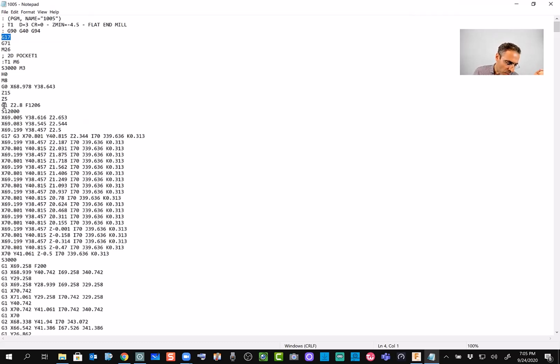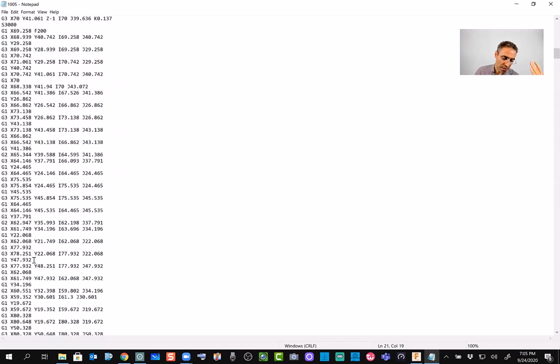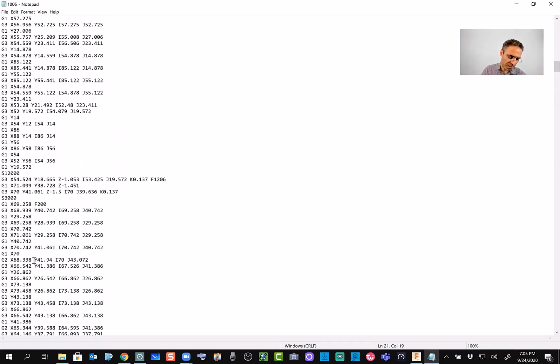At some point, it is just X, Y, Z. It's just the coordinates. You say, my first point is this X, this Y, this Z, right? And this is the I, J, K, which is the orientation of the tool. And then another X, Y, Z, and so on. All these things, the program has created for us.